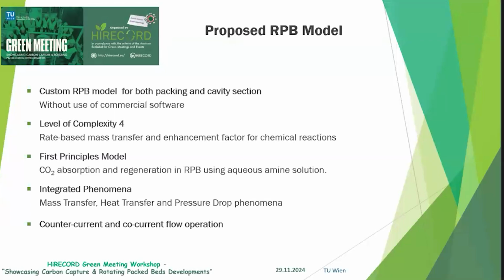As I have already explained, it is a first principles model that integrates both the CO2 absorption in the RPB and the regeneration system. It has all the occurring phenomena inside, with mass transfer, heat transfer, and a pressure drop equation, which is a vital equation for the system's performance. And it also has increased flexibility because it can operate in both co-current and cross-flow configurations.